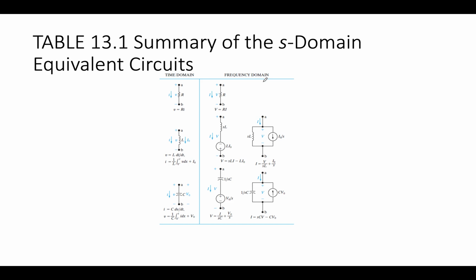Okay, let me comment about frequency domain. This is not frequency domain j omega. The frequency S is a complex frequency, which means it includes transient effects. So really, if I were writing this textbook, I would use this language, S domain, because it is Laplace domain. But S technically is a complex frequency, so it's okay to say it's frequency domain. I might say complex frequency domain.